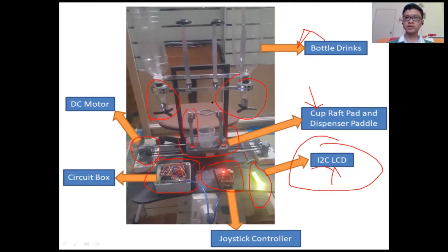The y-axis actually needs a heavier torque, because if you use a 0.8 kg torque motor, the pedal cannot rise. That's why I use 3.8 kg torque, which is about 870 rpm of motor, to make the pedal rise.